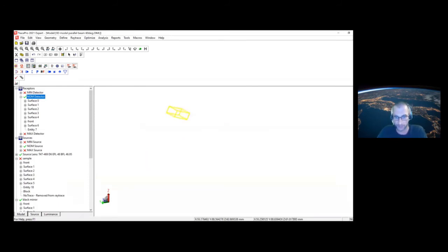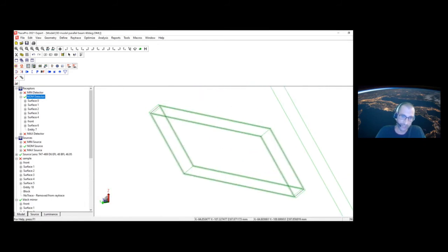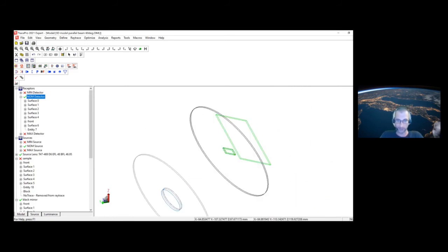And then if you zoom out, it's all at a 60-degree angle. This is your source lens. We can put a sample in place. Then we have our receptor lens, a baffle, and then this is the detector aperture. If I zoom in on this detector aperture, again, you can see different sizes which correspond to the minimum, nominal, and maximum size of the aperture as stated in the standard. And then behind this green square is your detector where we will capture the reflected light from the sample.